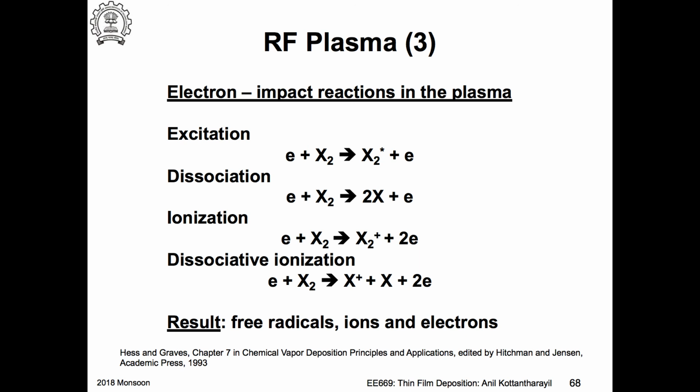Okay. And then you have an additional thing: you have ions, you can accelerate them, and that can also lead to sputtering. That's a physical etching. So you have three possibilities. One is a chemical reaction, CVD, deposition, and then there is a chemical reaction leading to etching, and then a sputtering process. In a CVD process, we had only two options. Ions were not present there. Thermal CVD, you could have deposition and etching. So here you have one more thing to play with.